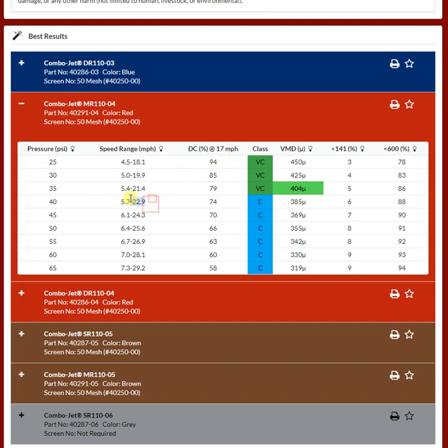So you might wonder why we might even want to have a max speed that high, to 23 mile an hour. And the reason being is that we want to ensure that we have flexibility. So flexibility in our ability to operate the machine, avoiding obstacles or keeping applications more consistent, and generally taking advantage of turn compensation mechanisms within the sprayer system as well.